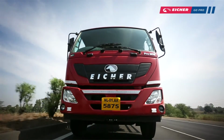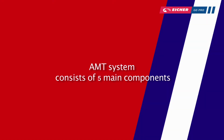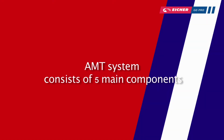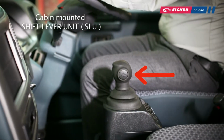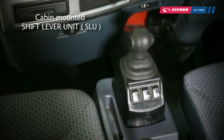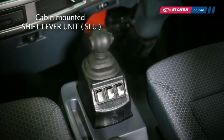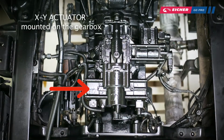Covering nearly all applications of trucks and buses, the AMT system consists of 5 main components. 1. Cabin mounted Shift Lever Unit, SLU, including the system's electronic control unit. 2. XY actuator mounted on the gearbox to select and shift the appropriate gear.